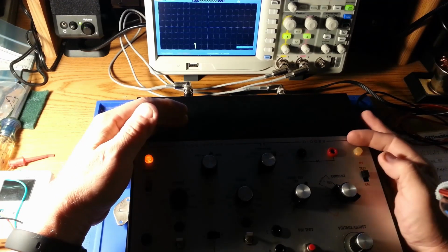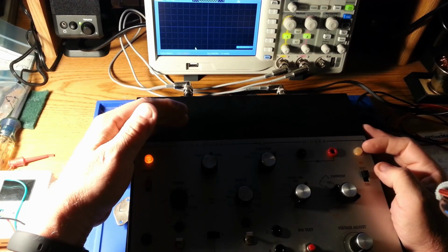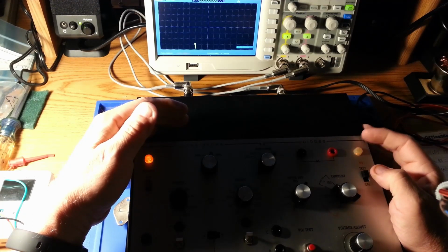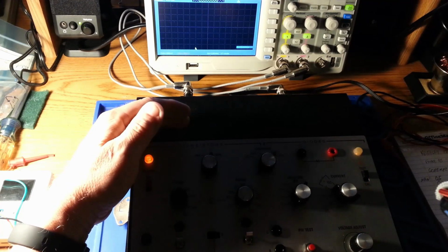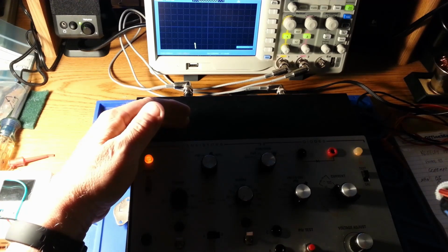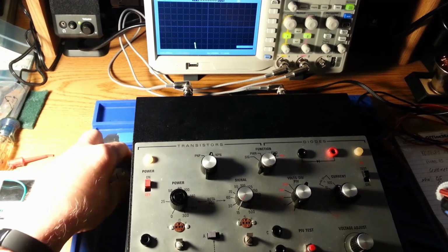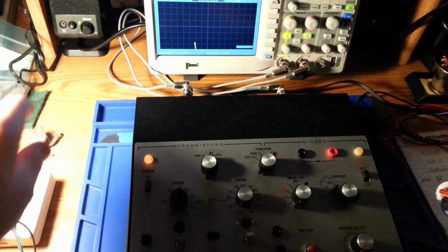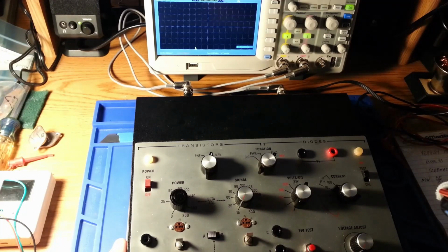and it leads me to believe that although this does have an indication, it might be oscillating so fast that it's actually cutting down the voltage. And I'm also not sure of the shape of this bulb. I'll have to do a lot of investigation on it, so I'm basically going to have to turn this thing over, gut that whole circuit, maybe breadboard it, and I can use my Eico 1140 substitution box to do some in-circuit variables while it's live, in order to try to figure out what's going on with it. I just would not like to run into any problems.